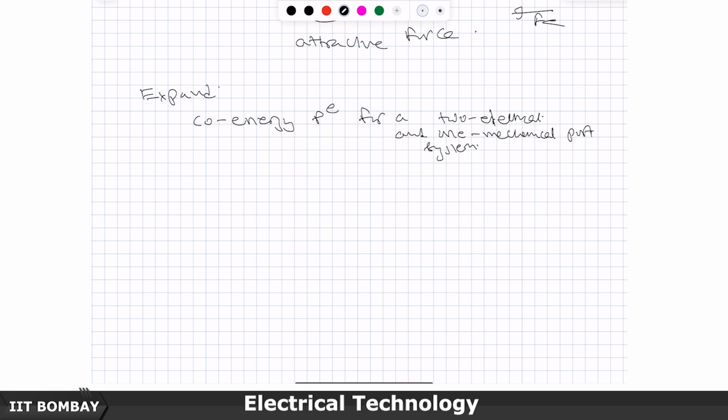development of the treatment. So, if you have a system like this, then lambda 1, strictly speaking, will depend upon its current. Mutual coupling will be there because there are 2 sources now on the magnetic system. The magnetic system is excited by 2 sources. So, I1, I2, and of course, it will also depend upon X, which is the coupling between the 2.